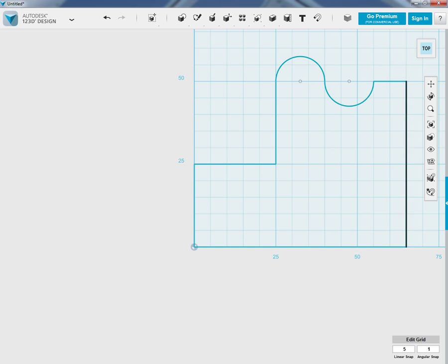So if I mouse over these lines, you'll notice that it's selecting each line separately. But this first set of polylines that I drew, straight lines and curves, is all one sketch. This line down here is a different sketch, and that's really significant. So I'm going to select this, and I'm going to hit the delete key on the keyboard and get rid of it. Let's come back to that tool again, the spline tool.